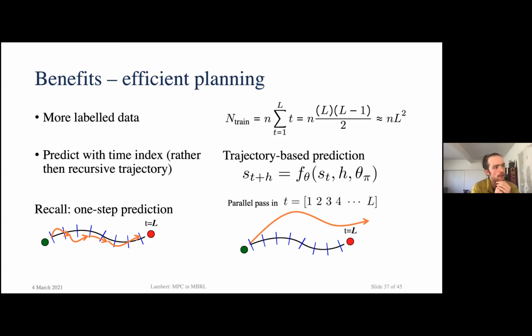But with the Reacher task, we had different positions in the 3D state space for where your arm wants to go, and the PID can encode that by having different target joint angles. A joint angle of 60 versus 30 gives a much different parameterization of the arm. I'll talk more about that parameter later, but it's one of the big limitations of the work, needing that parameter.